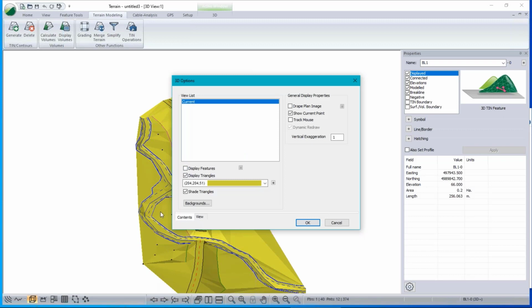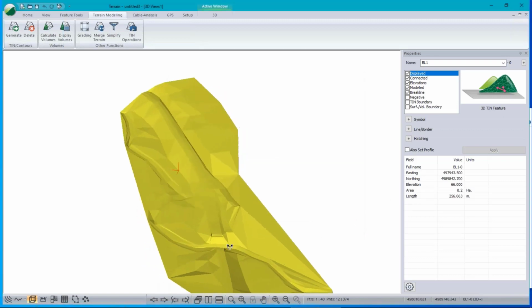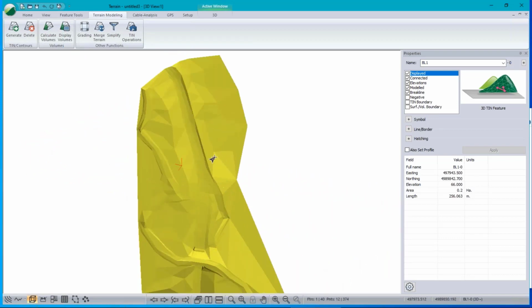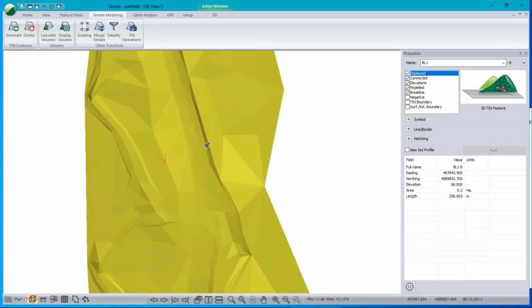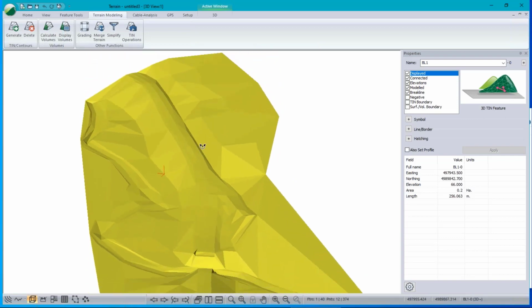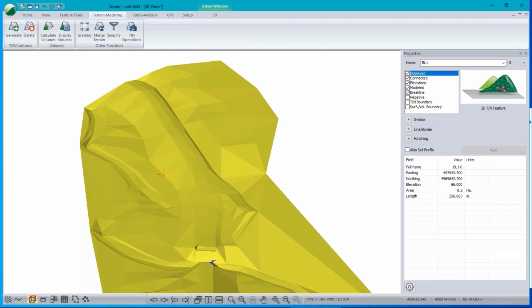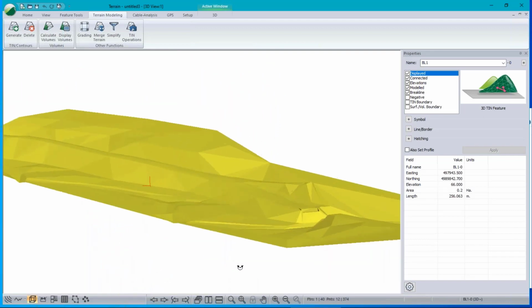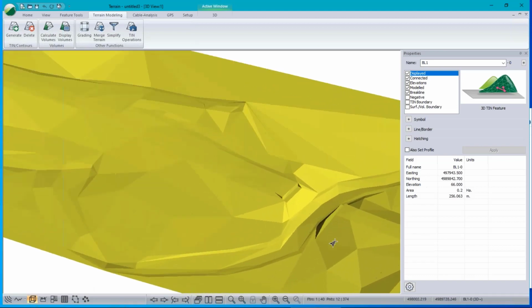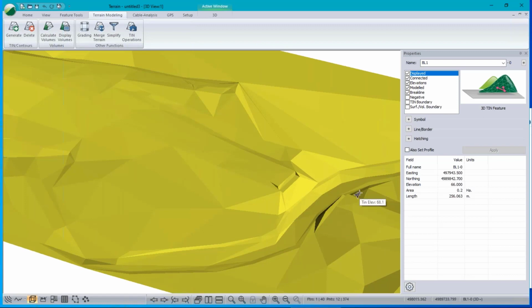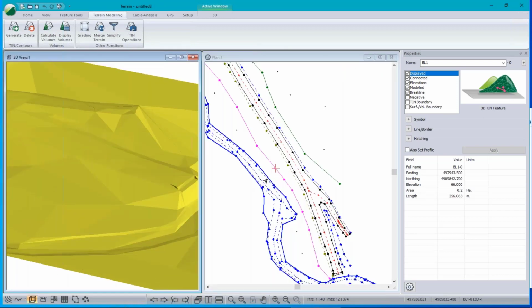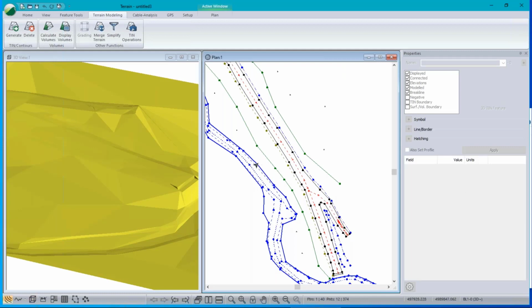display of the features, which is giving me a lot of hints here, you can see clearly that this is a nice smooth model. Although it's still made of triangular facets, they seem to be organized in the right way to define a nice smooth roadway, a creek bottom, and look, there's a crossing here. You can see that this is a bridge abutment. So that's the magic of break lines. When we have break lines that are defined, the software will build triangular facets that align with the break lines. And as Aaron says, that means the elevation along the break line is interpolated between the data points and is actually a straight line between all the points.